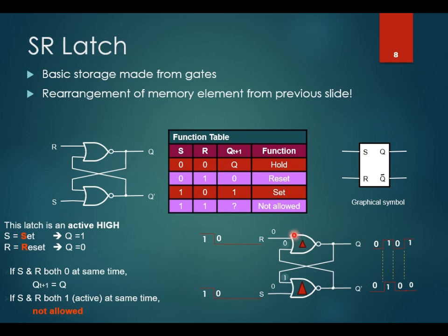So remember, the race condition is because the two NOR gates keep observing the same value along with R equal to 0 and S equal to 0. But if a slight delay produces Q bar slightly late, the accumulated delay will eventually cause two different values to be observed by the respective NOR gates, and it will settle Q and Q bar to the complement values. As shown in this figure, it will settle to 1, 0.